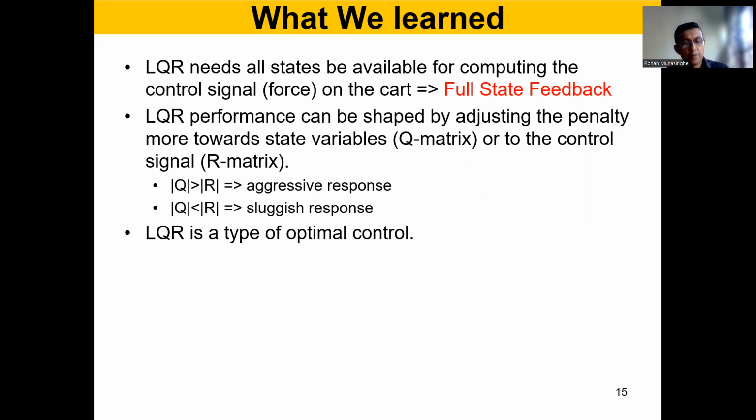Or if you set the R matrix big, like 100, 150, and then the Q matrix elements are small, 10, 20, like that, then we say that it's very costly to have big control signals, because R big means cost is high for controls. So we want to reduce R as much as possible. But there's no big issue with having big signal variations. Before you are stabilizing, the signal goes up and down. So that's okay.